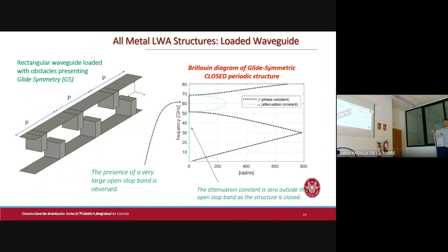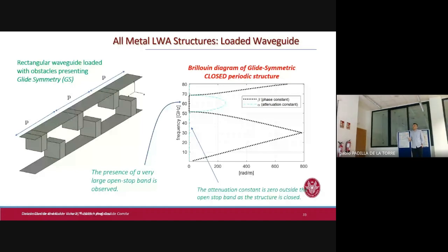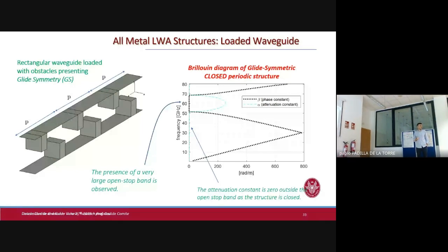And I have the proof with a student that you are working with on this topic. We can get at least 10%. That's right. And probably even 15, and then it depends on the directivity they ask. For sure, here there is almost no difference between directivity and gain, because up to 100 gigahertz losses are essentially absent. So you just need a good feeder, fully integrated. Then you can say, okay, I want to reach 40 dB with a small bandwidth, or I want to take 30 dB with 10%. It depends upon the application.